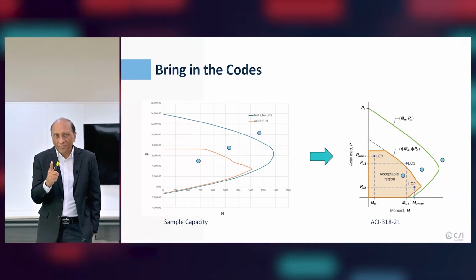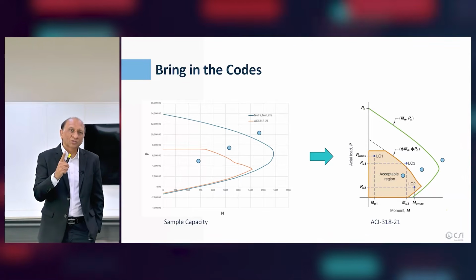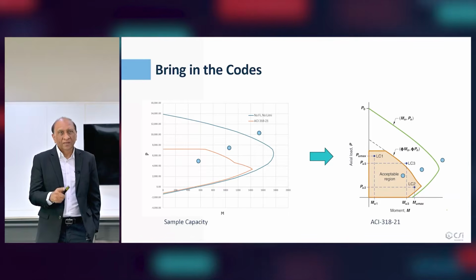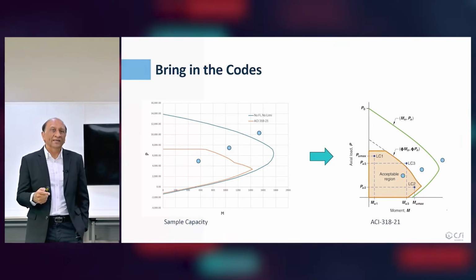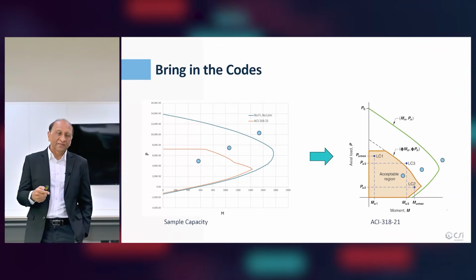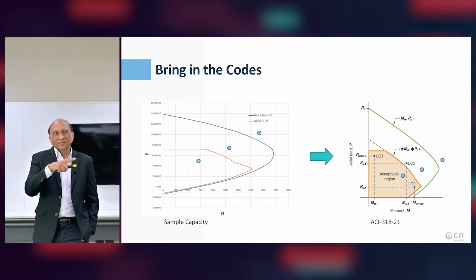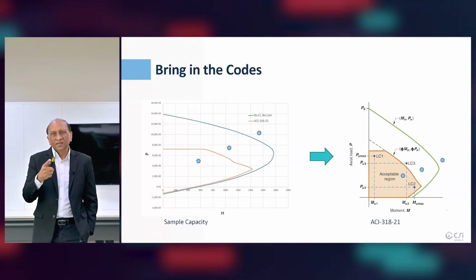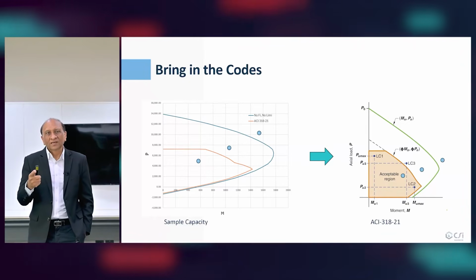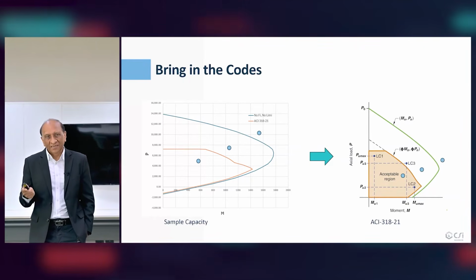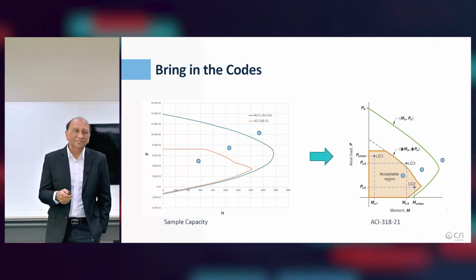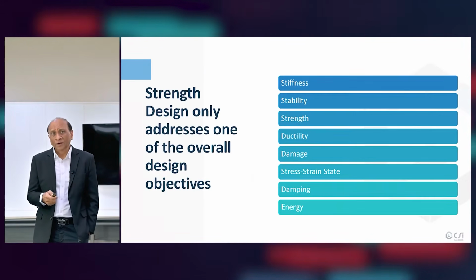But this is only unsafe if the strain of concrete is considered to be 0.003. But the actual strain capacity of concrete is not 0.003. It can be much larger. So that means this capacity-based approach is not very useful when we talk about the real state of the cross-section and real available capacity. So let's move on.